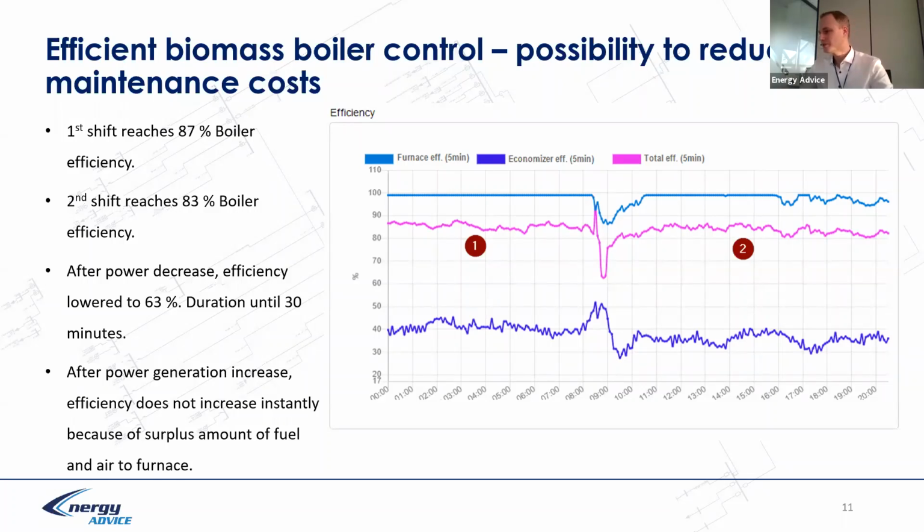During its half-an-hour event, the operator was not capable of making a real reaction to the process, and the control system was not capable of this either. But here the operator seems to make a reaction, and when the thermal power demand increased, the operator increased fuel supply. The automation system also increased it, because the operator is just changing set points, but the SCADA system is in fact supplying the fuel.